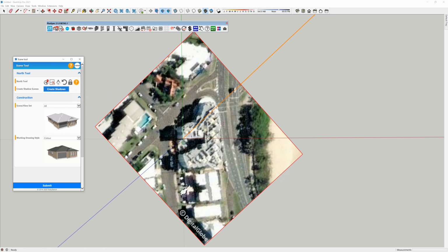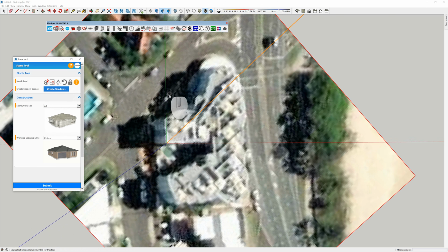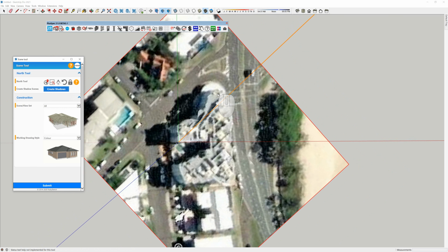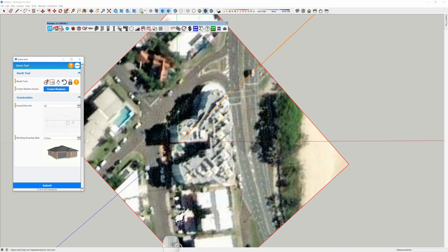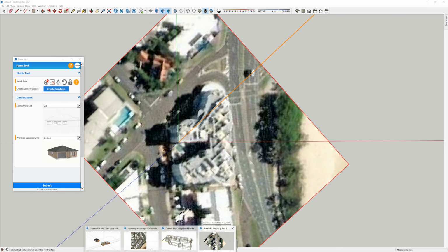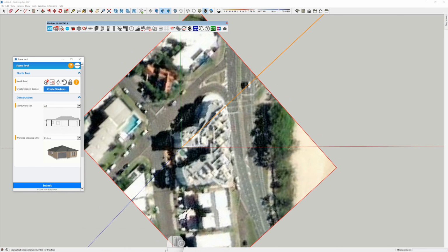So once again, it's really important to set up your model axes to align with your image. I've seen people actually draw full projects off axes and then it's just a nightmare and they basically throw it away and start again. Really, really important. Okay, so let's just have a quick look at the difference in resolution between the free and the purchased, and then I'll leave it up to you to decide whether you think that this is the best option for you.